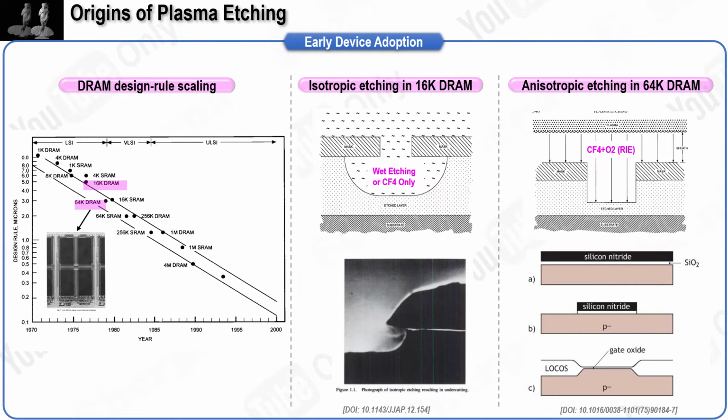By the mid-1980s, reactive ion etching had replaced most pattern-defining wet chemistry in very large-scale integration, while liquids remained for targeted cleans and stripping. That is how plasma etching entered device fabrication, first as a cleaner and then as the method that delivered directionality and repeatability for scaled features.